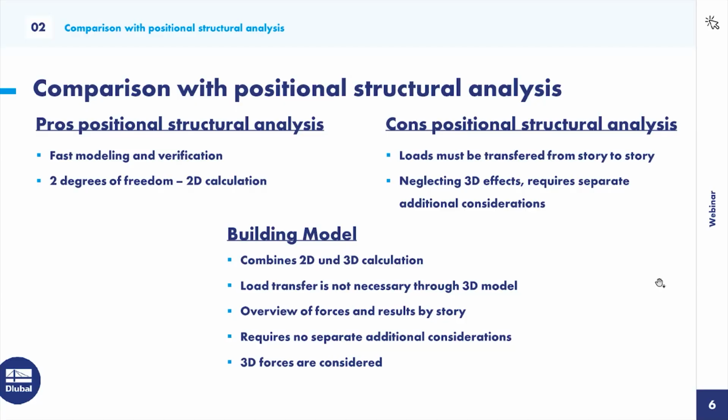The cons are when you design a slab or, let's say, a story, you calculate this, then you must make a load transfer from the story to, let's say, the walls, to the columns, and from there again to the slab. So you must all the time transfer new and new again until you are on the ground floor. And yeah, there you can make failures very easily when you forget some loads.